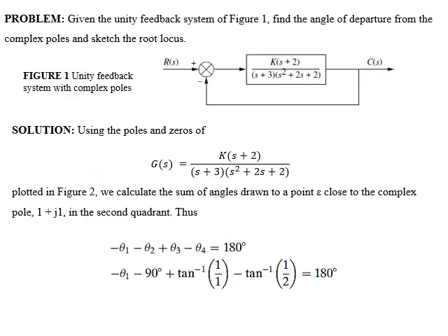Dear students, now in the given example we will find the angle of departure for the complex pole in the system and we will also sketch the root locus.